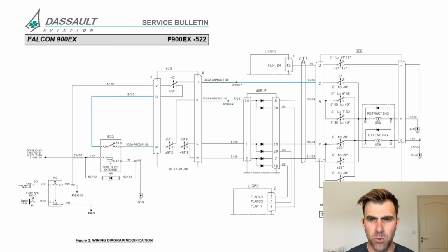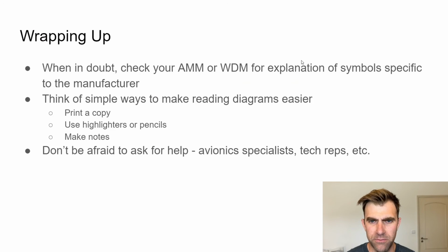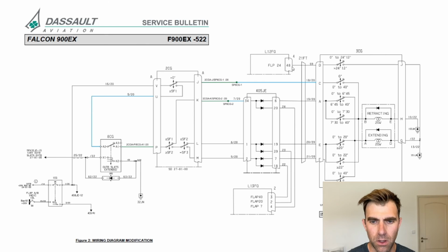And well, one more thing here. I just saw this here, 21 FT. I do know that this FT is a feed through. There could be some cases where this little symbol has no numbers within the rectangle that's going around it. That indicates that this is just a feed through. So it's a bung that the wires are passing through, like a sealed bung.